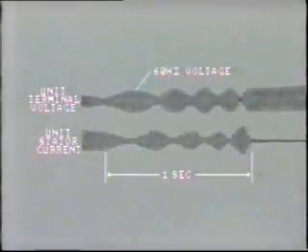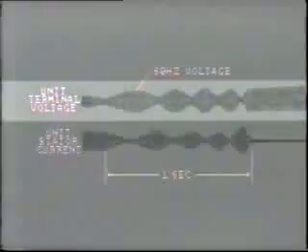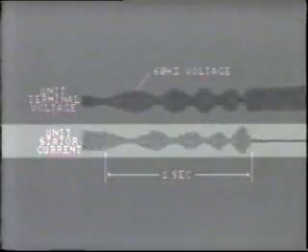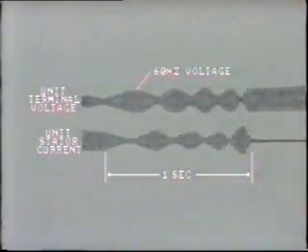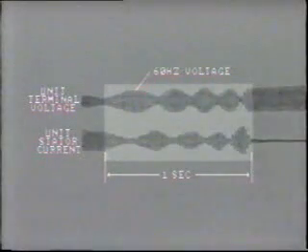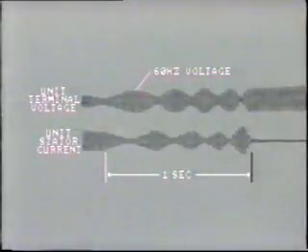current. This example shows generator terminal voltage and stator current recorded on a conventional fault recorder in the power plant. In this case, the unit lost synchronism and began slipping poles after a major tie line was opened. The recording shows about 1 second of the disturbance. At this point, the generator trips offline.